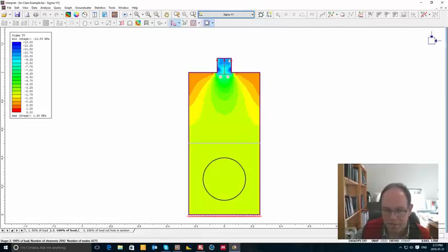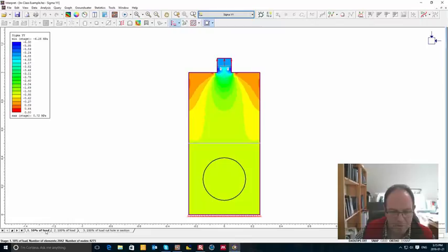Okay, and if we have 1 meganewton across 0.5 meter wide section, that corresponds to a stress of 2 MPa. Okay, so this green is around 2 MPa, and it's a fairly uniform, similar to St. Venant's principle. So that looks to be right.